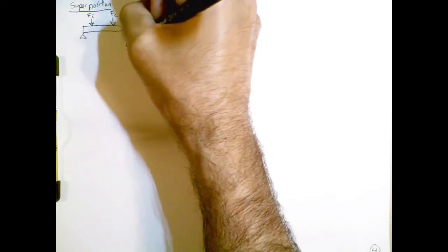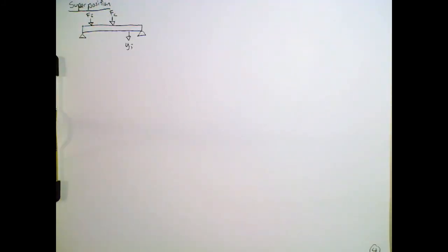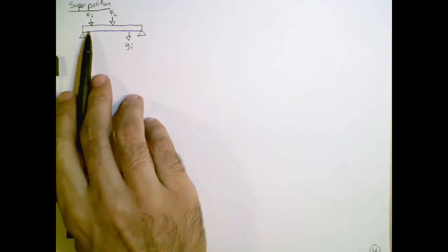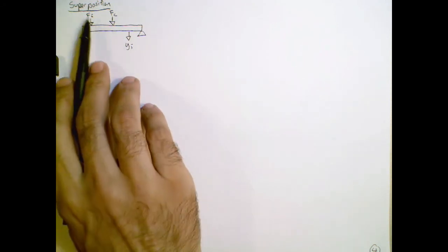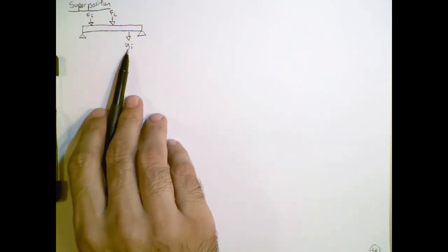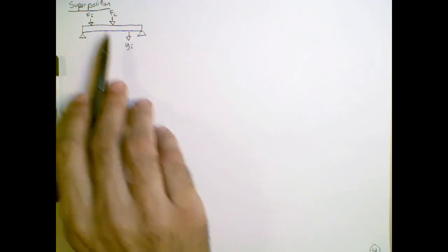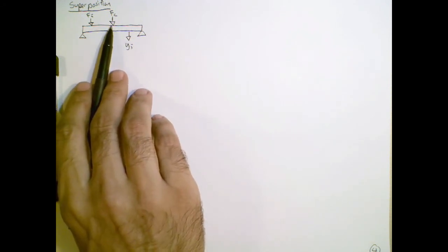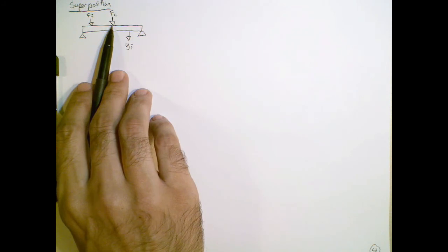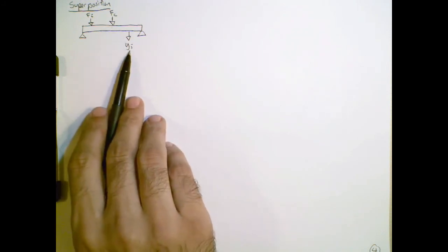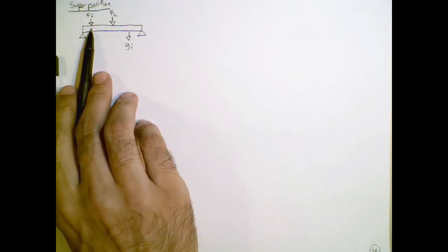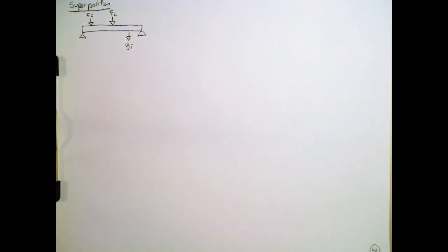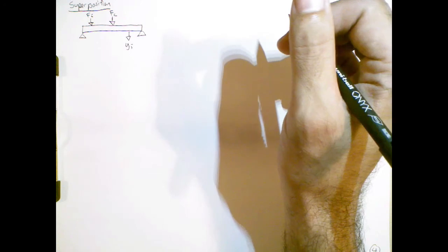another location, yj? So we can derive for a simply supported beam what's the influence coefficient that's going to relate Fi to yj. But can we come up with a force that is applied at the center that will produce the exact same deflection at location j that Fi would have produced if it was applied at location i? Okay, so how do we go about using this observation?